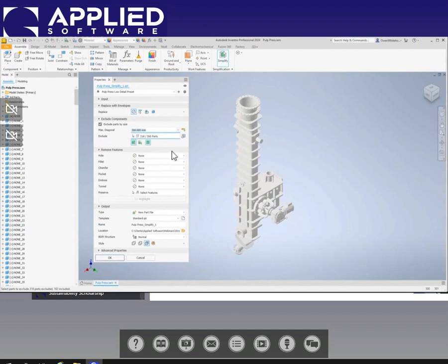It's normally too much. The other thing I like to do is go in and exclude parts by size. And this one's kind of fun. You have to play with it. But while you're doing it, you can hit this little button right here to show excluded parts. So you can change the size, and depending on the units, this can be in inches or millimeters. But as you pick your various sizes, you can hit this button here, and it shows you the stuff that's going to be excluded from your model.